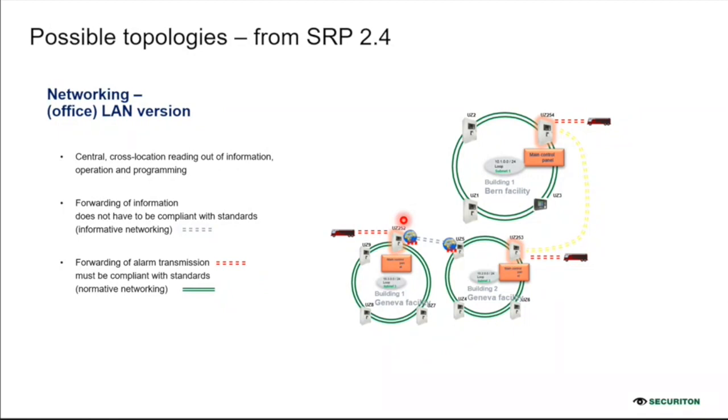The next and the last question is, is a temporary lockout of a sub-control panel possible from the overall system? For example, during maintenance, such things are necessary. Yes, whenever you realize a SecuriWan, from the SecuriWan main panel you can switch off a sub-control panel, and you don't receive information for that sub-panel anymore. So whenever you go on site to make maintenance, you can work on that sub-panel without receiving messages on the main panel.